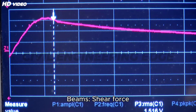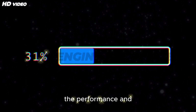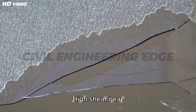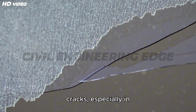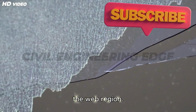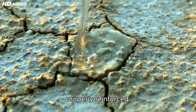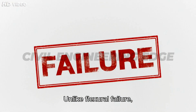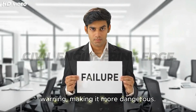Effective shear in RC beams. Shear force significantly affects the performance and safety of RC beams. High shear near supports induces inclined or diagonal cracks, especially in the web region. These cracks can lead to brittle failure if not properly reinforced. Unlike flexural failure, shear failure occurs suddenly without much warning, making it more dangerous.